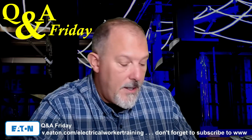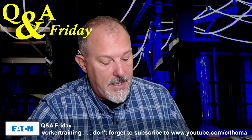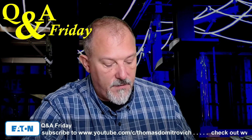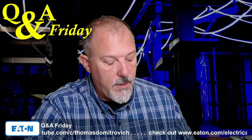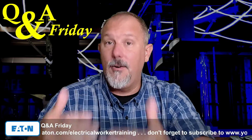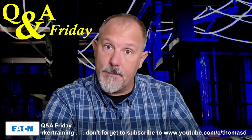Okay, so what JW references is in 210.8 A and B. Like in A, it says all 125 volt through 250 volt receptacles installed in the locations specified in A1 through 11 and supplied by single-phase branch circuits rated 150 volts or less to ground shall have GFCI protection for personnel. That is a little different than saying an outlet, because when I say an outlet, there's nothing in there. If I put a receptacle in that outlet, it becomes a receptacle outlet.